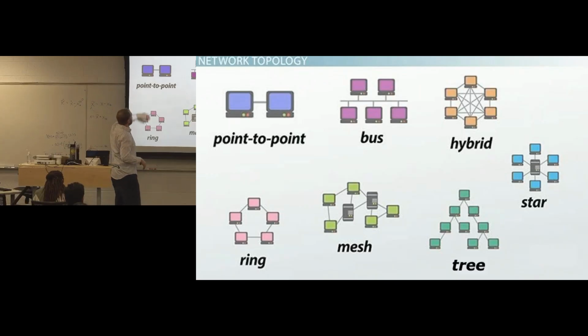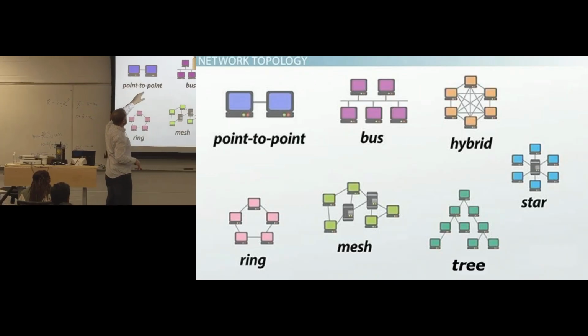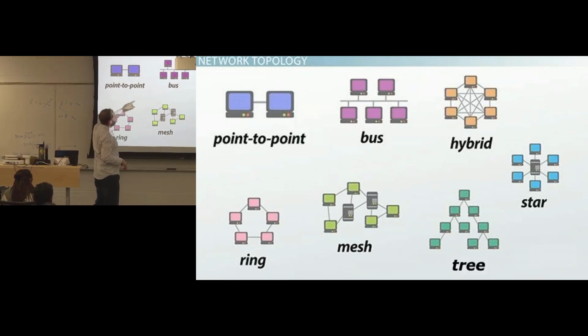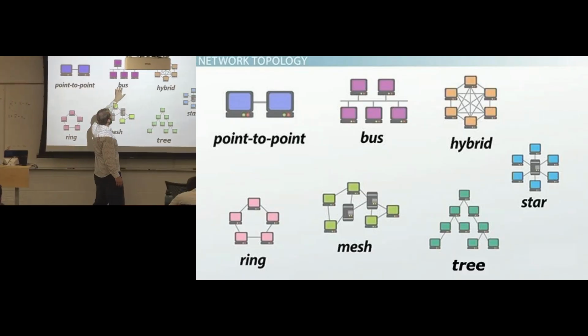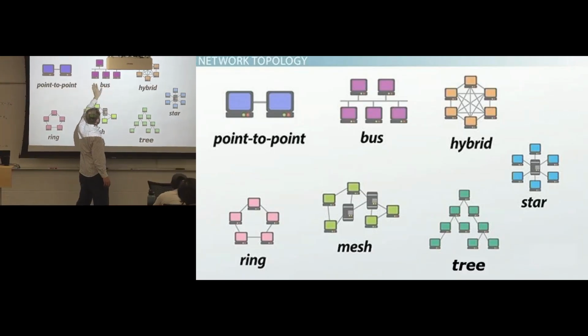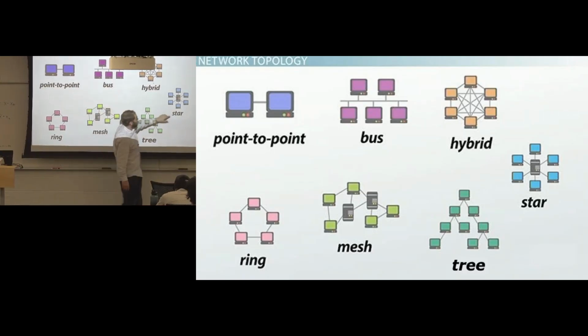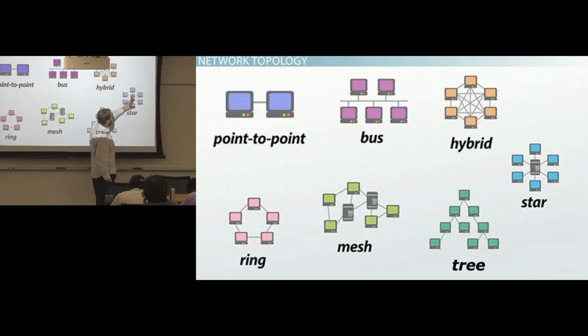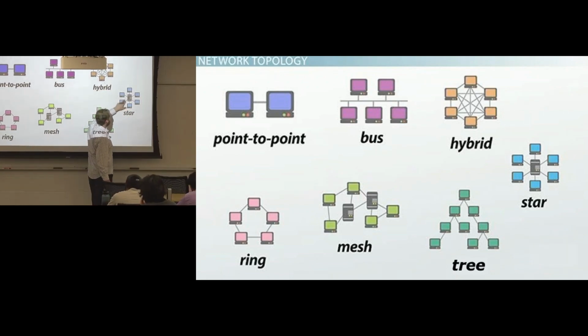And here's just a visual example. I don't know why these come out so bad on the screen, but this would be like UART, where you've got point-to-point communication. Many structures are like this, where you have a common bus that goes between them, but you could also think about a star configuration, where you're the microcontroller and now you're talking to multiple different devices. Oftentimes you have dedicated pins, like 2 UART pins, or 2 sets of UARTs, 2 sets of I2C, and you can think about a star configuration like that.